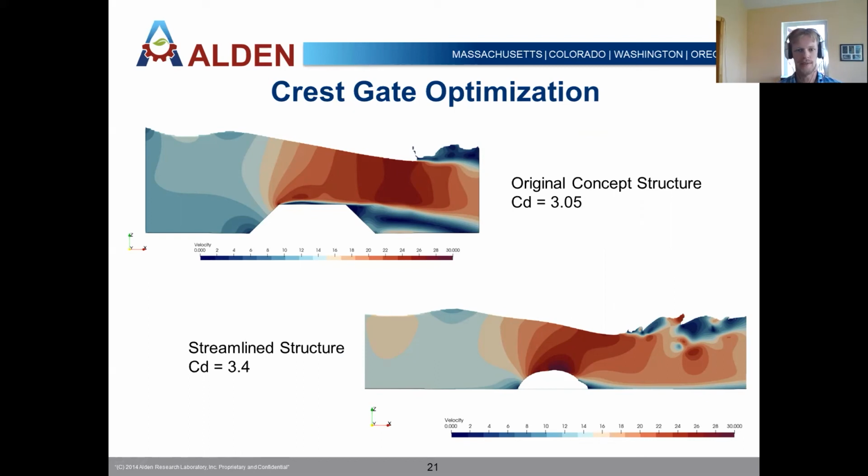And it was actually quite useful for proposed conditions, where we had to create this adjustable grate structure to compensate for the loss in spillway. Initially, this shape was created with just this trapezoidal section, and by running the vertical slice simulation, you could get a discharge coefficient of 3.05. But you can see a flow separation region just on top of the structure, and then a huge one behind it. Those recirculation regions cause drag and reduce the efficiency of the structure.